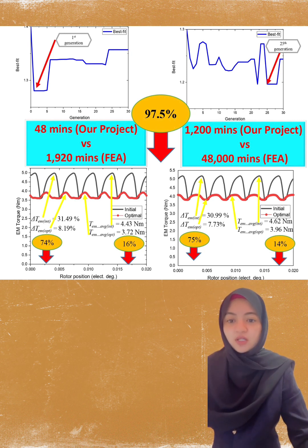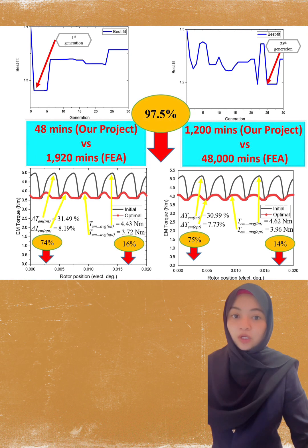And the framework of subdomain model and GA is competent in minimizing the usage of magnet material, as well as the ripple in the design of PMSM, which brings benefit with lower cost imposed on the motor during the fabrication, and the PM motor becomes lighter.